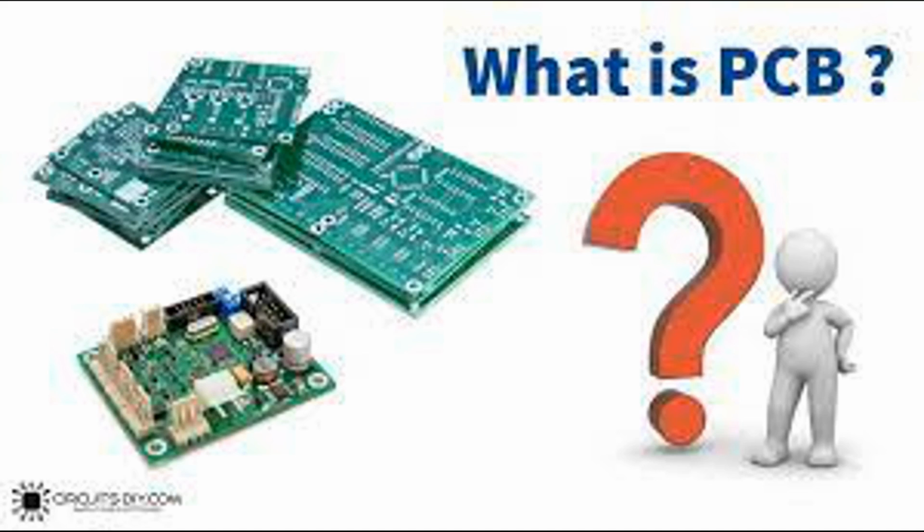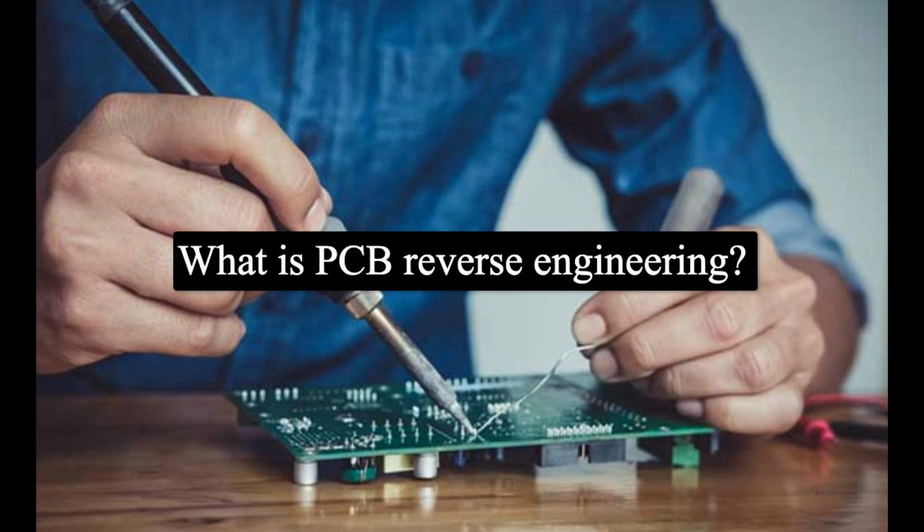Polarity and orientation. Silkscreen markings can indicate the correct orientation and polarity of components that must be placed in a specific direction, such as diodes, LEDs, and polarized capacitors. This helps ensure that components are installed correctly.